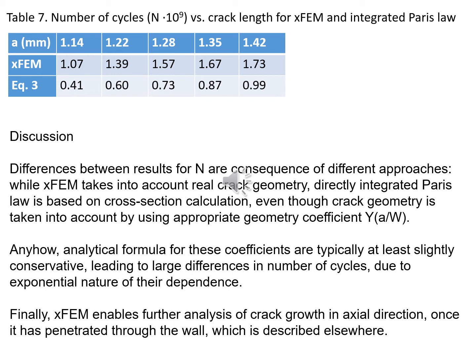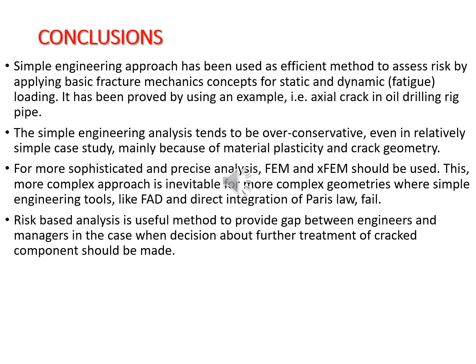So we definitely need FEM if we need more precise results. But on the other hand, if we are satisfied with over-conservative approximate results, very simple direct integration of Paris law can be quite useful and efficient. So we come to the conclusions.